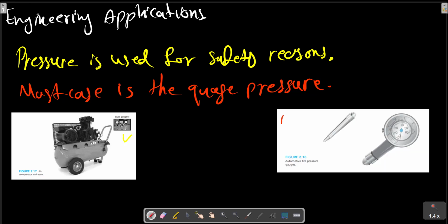A pressure gauge is connected to the valve stem under the tire. For example, some gauges have a digital readout. The tire pressure is important for the safety and durability of automobile tires. Too low a pressure causes large deflection and the tire may overheat. Too high a pressure leads to excessive wear in the center.